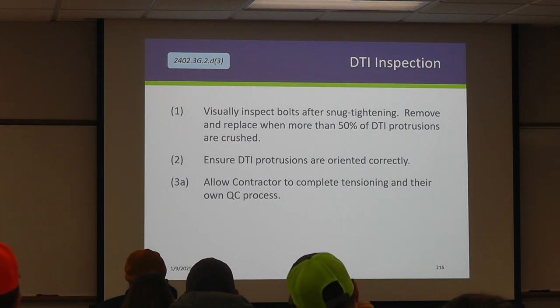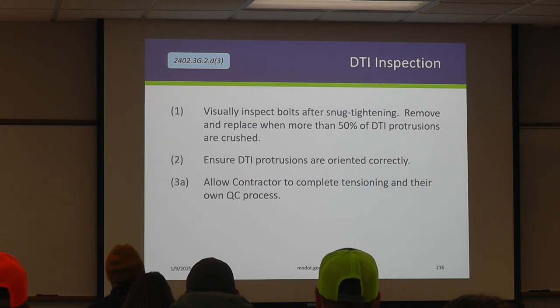You have to make sure that the DTIs are oriented correctly in the correct spot, and that the contractor has followed their QC plan. They should come to you and say, all right, our snugging's done. We followed our procedure, will you go check it? This isn't something that you should be bird dogging.